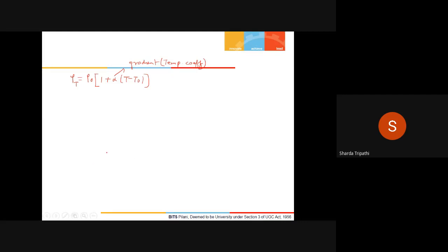Okay, so now we have the formula for the conductivity and the current density in case of metals. So if I get back to the formula for the current, from the formula for current density, I can say that I is equal to J multiplied by A. You substitute the expression of J, this will be equal to sigma into E into A. So let me just multiply the numerator and the denominator by L and regroup this a bit. So this will become sigma into A divided by L multiplied by E into L.